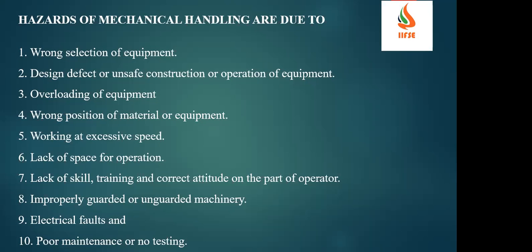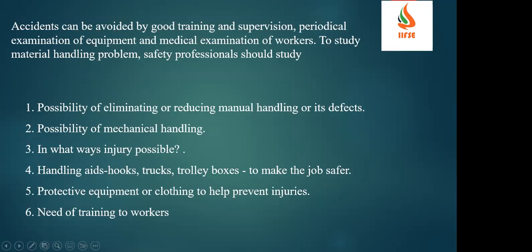If required, all the lifting tools and tackle need to be calibrated by the Department of Factories approved consents. Some items are covered under once in 6 months, and some under once in 12 months. So this testing has to be done, and we need to get the Form 9 (FITS) certificate from the competent person. These kinds of things they do not take care of until the equipment gets shut down, or until it meets with an accident. These are the hazards.